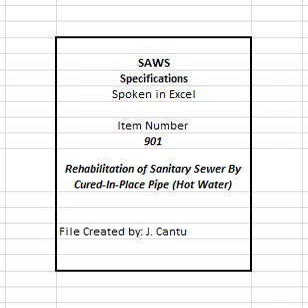Chemical solution with concentration %. Tap water pH of 5 to 11. Acids pH not less than 5.0. Gasoline total BTEX limit of 100 mg/L. Oil and grease 50 mg/L. Total phosphorus 40 mg/L. Sodium hydroxide and other strong bases pH not higher than 11.0. Ferric chloride 3 mg/L. Sodium hypochlorite 3 mg/L.